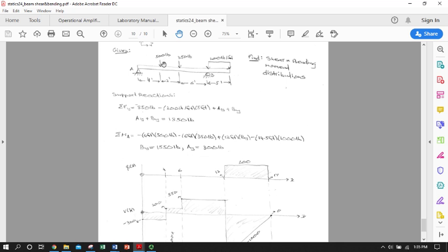Then when we add a 500 pound downward load, the shear is going to shift up to basically balance the forces in the y at that point. So it's going to shoot up by 500 pounds, and it's going to stay at a constant 200 until we get to this point, and it's going to shift upward again by 350 to balance the new load. So now it'll be at 550 until we get to point B effectively.